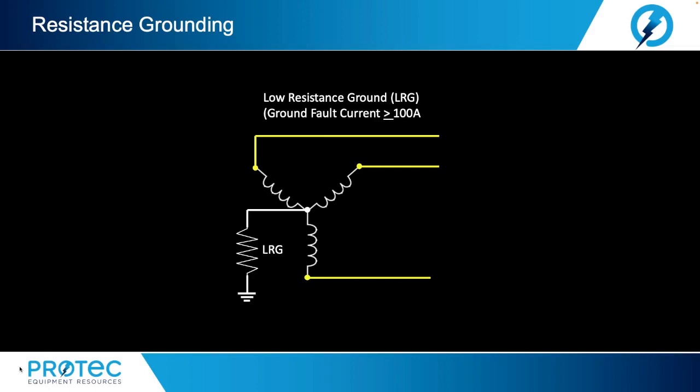Since the grounding impedance is in the form of resistance, any transient overvoltages are quickly damped out and the whole transient overvoltage phenomena is no longer applicable. This method is employed on 2400 volt and 4160 volt circuits. The low resistance method has the advantage of immediate and selective clearing of the grounded circuit, but requires that the maximum ground fault current be large enough to positively actuate the applied ground fault relay.